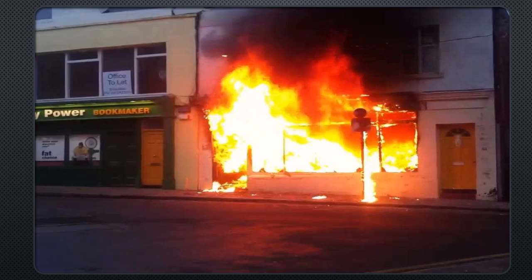If I'm responding to a residential box in my first due area, and I know that every house in that box should be a single family residence, type 5 construction, I don't need to pull up on location and say, I'm on location with a type 5 wood frame building, single family residence, multi-floor building. It's assumed if we're going to a residential box that we're pulling up on a type 5 construction building. However, should I respond to that same box and find myself with a type 3 ordinary construction building, I need to reiterate that. That's something I should get out on the radio.